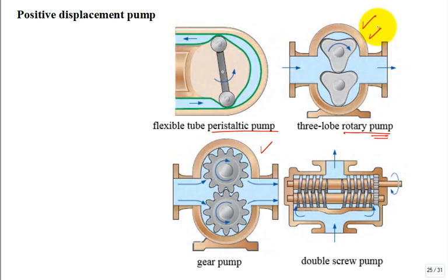This many people? The water pumps are more centrifugal. But an oil pump, the engine wants that oil, and a little bit of resistance to the delivery of oil, and a positive displacement pump says, I'm going to give it to you. You need the oil, here it comes.